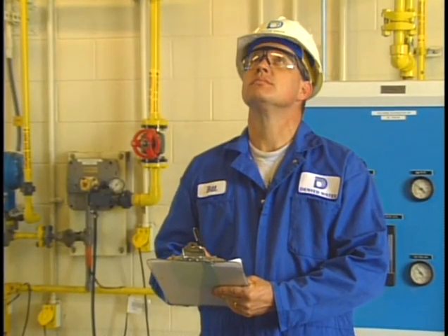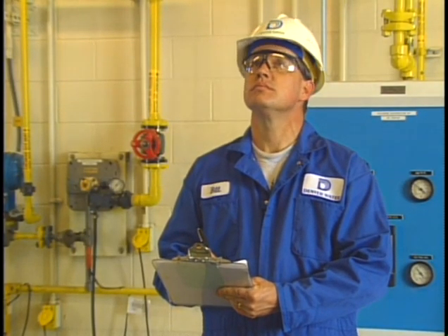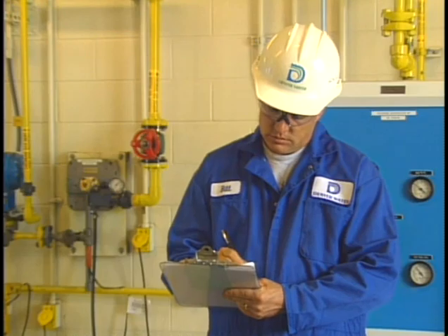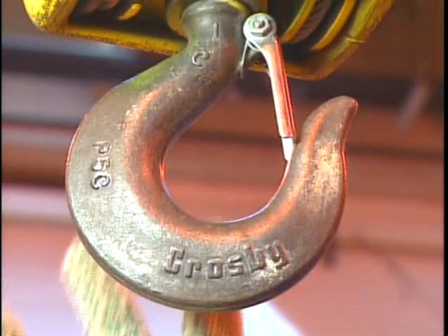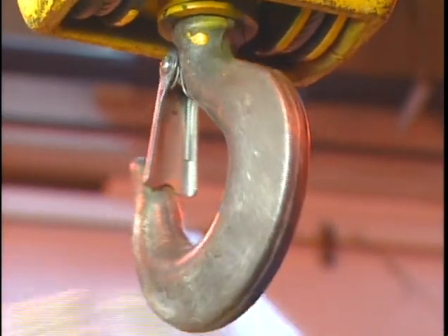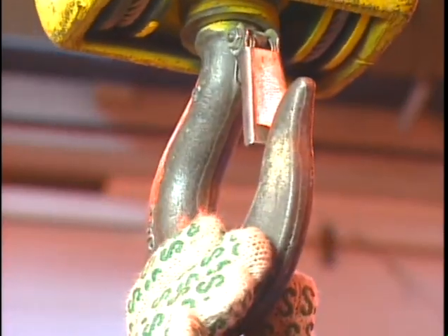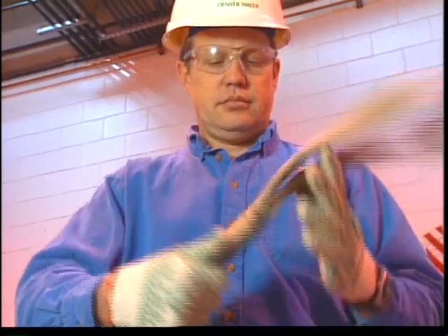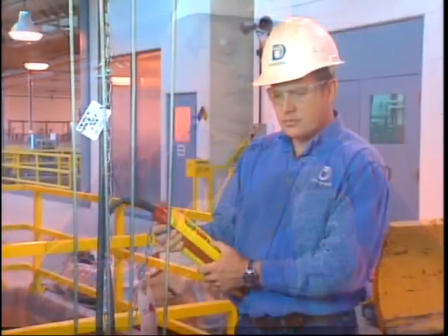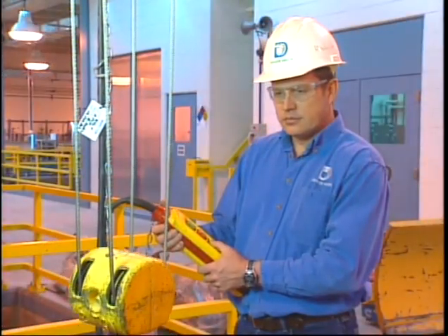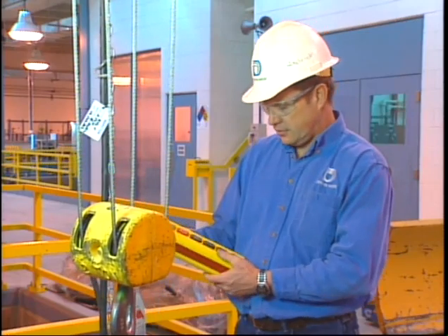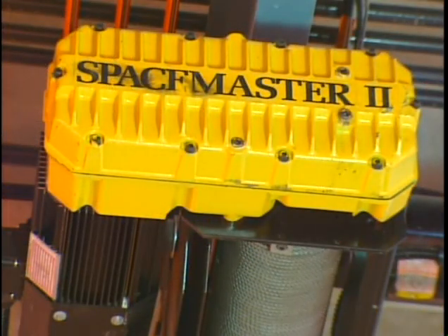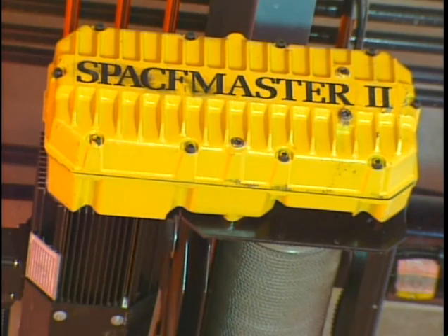At least once a month, a qualified inspector should also examine the equipment and make a written record of the inspection. Frequent inspections include: check the hook for cracks, examine the hoist chains, ropes, straps, and slings for excessive wear. Check all operating mechanisms or pulleys for proper alignment and operation. All exposed moving parts, such as gears, should have guards or shields in place.